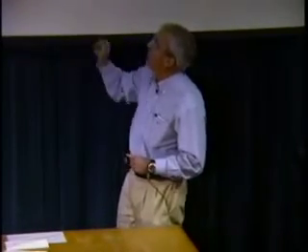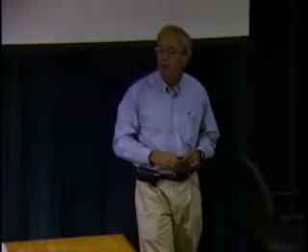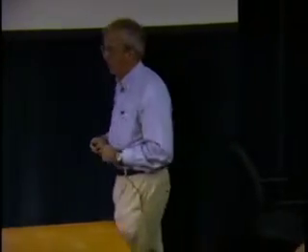Because if you try to get the bandwidth to feed these floating point units off chip, it's prohibitively expensive. It's $8 per gigaword per second, if you look at it that way, 16 times as expensive. So you don't want to transfer all those words off chip. You need at least a 20-to-1 ratio of operations performed on chip to words per second of off-chip bandwidth. And by the way, since each of those operations requires 3 operands, 4 for a multiply add, you actually need to multiply that number up again by a factor of 3 or 4.